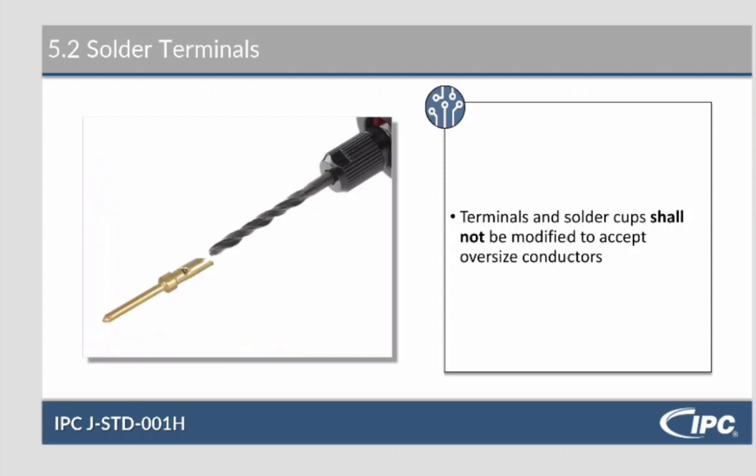Okay, terminals and solder cups shall not be modified to accept oversized conductors. If you have to modify your wires or your components, you have either the wrong wires, the wrong components, or the wrong engineering.